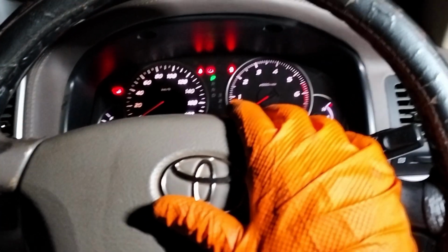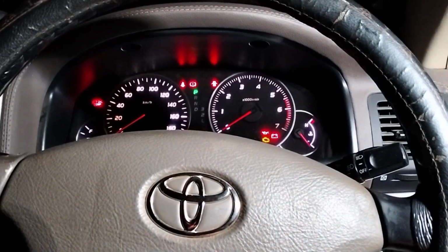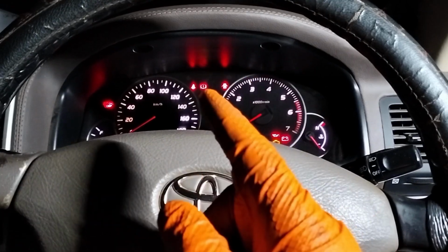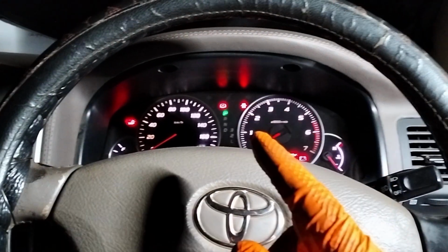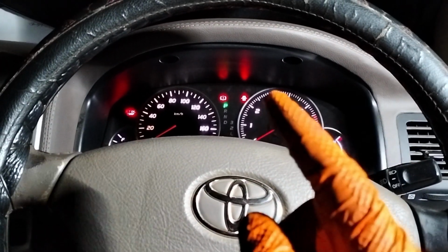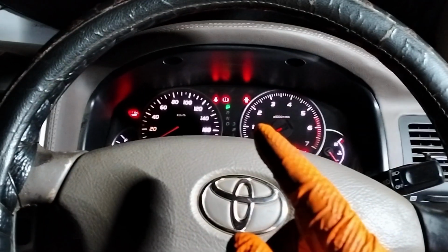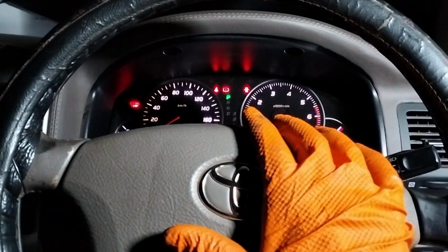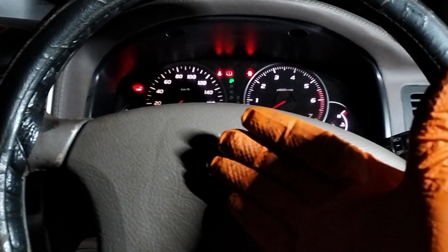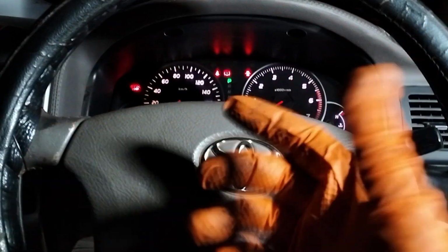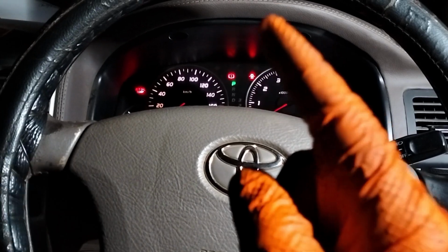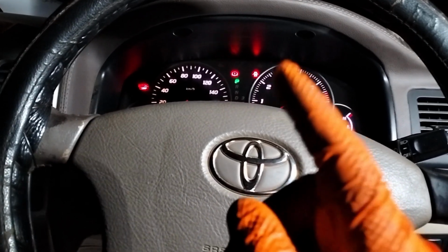Wow. Nice diagnosis. I love this one. I've learned a lot about the window switches and the window motors. When you see motors with the Hall effect speed sensors, they are for anti-pinch control. And that is really, really cool. Now, guys, part numbers exist for a reason. Here in Kenya, I see a lot of shenanigans happening. People think that just because one part looks like another, you can just interchange them. You are in for a rude shock, and sometimes it can be catastrophic.